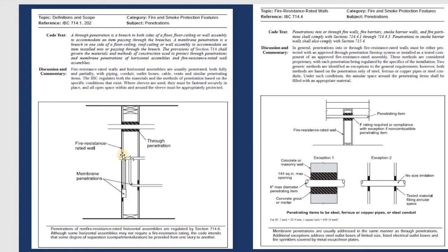You need to be concerned with the construction group, and whether it has a sprinkler system or not. In some cases, if you have a sprinkler system, you can reduce the hours of the fire resistance rating on this side.